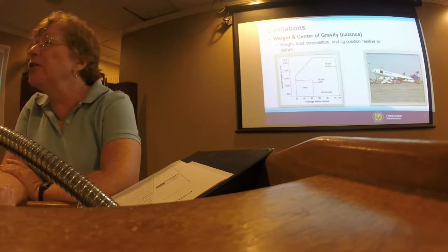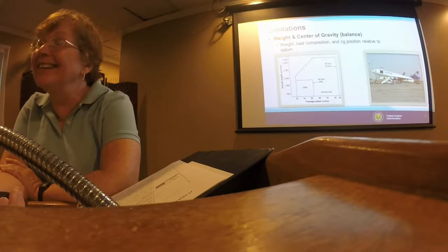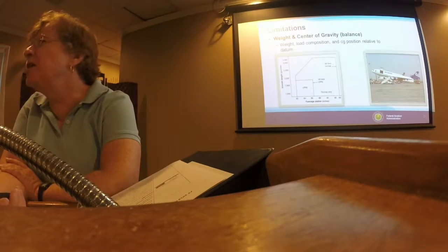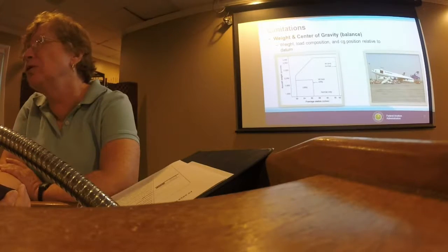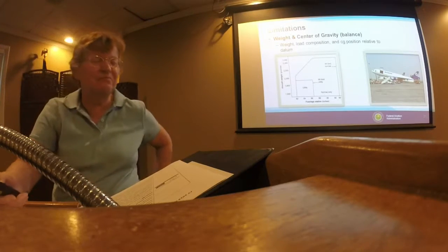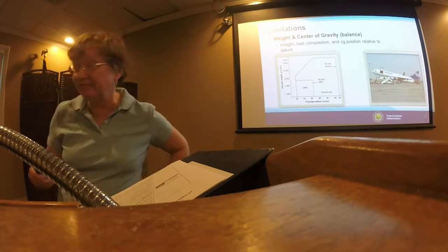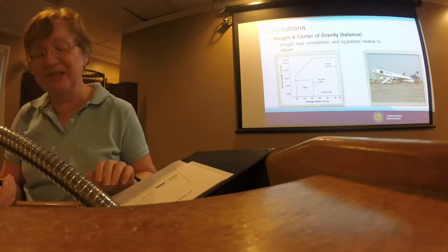What happens if we're outside of the center of gravity? Let's say we're too far forward. If we're too far forward, it may mean that we cannot raise the nose. Which one is it? It's raise the nose, right? And too far aft, we might not be able to lower the nose when we need to. And the airplane might fly funny too.